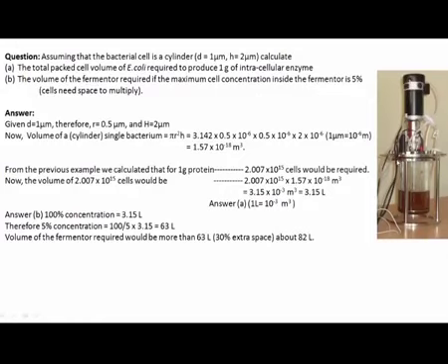You see, you cannot have the entire volume of the fermenter packed with cells. If that happens, then the cells have no space to grow, there is no aeration, there is no movement, nothing can happen, and therefore the cells will automatically start dying. So the fermenter requires a lot of breathing space, a lot of air space, and also other spaces for the bacteria to grow. This space is the head space, and as is said, only 5% is required. So, let us now start calculating.